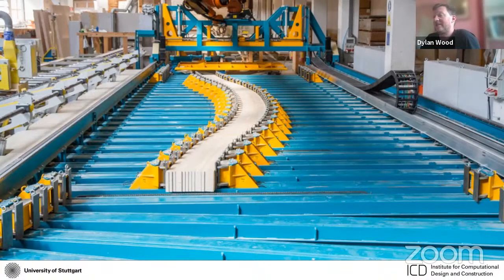So often it's cheaper to just use a straight sheet with twice as much material than it is to make a curved piece. Or it's even less desirable, at least from our perspective, in that it's cheaper to just build a square piece and then remove material from it until you reach the specific curved geometry that you want. Of course, this is not ideal from an ecological perspective, but it also is not ideal from a structural perspective, because it means that you end up with many fibers that are oriented in completely the wrong directions for taking the load.